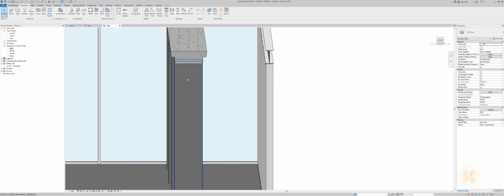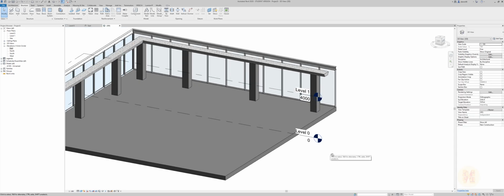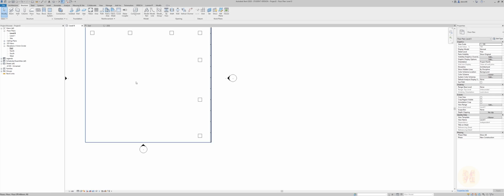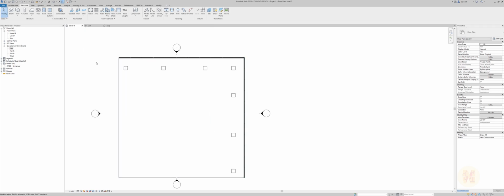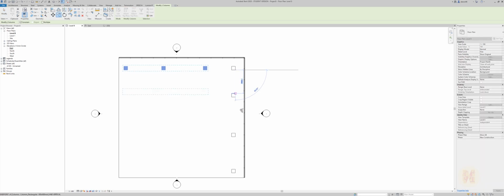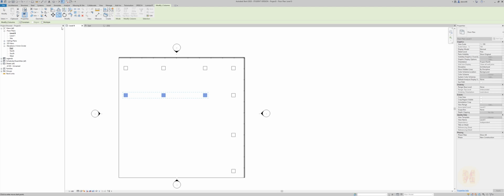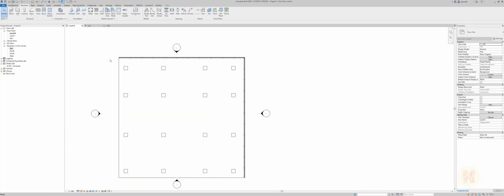And in a few seconds, as you can see, here's our beam. We spent just a few seconds to create this beam and this plan. Let's go to the level 1, to the levels, and now I want to copy this column. We will copy it inside our building. Let's use copy multiple, because I'm too lazy to select this tool again.